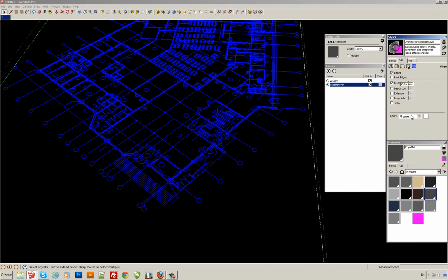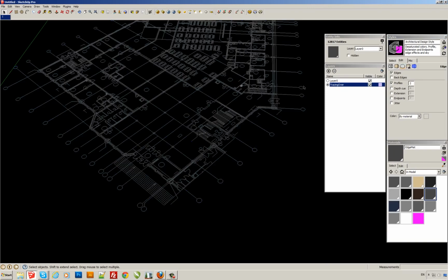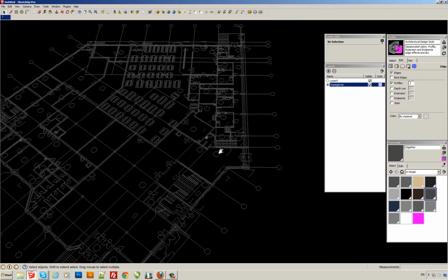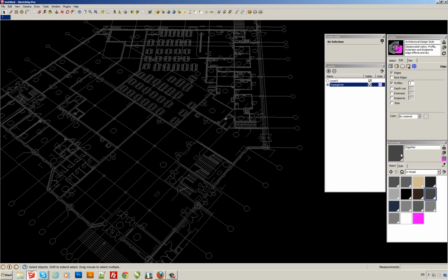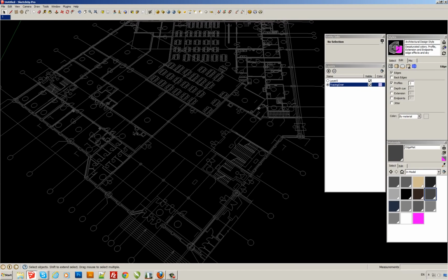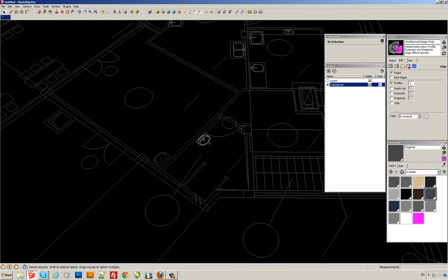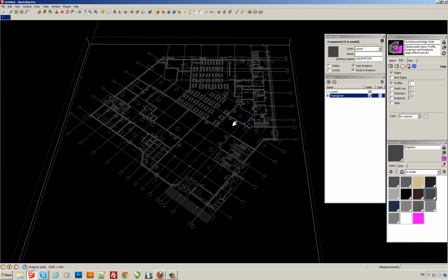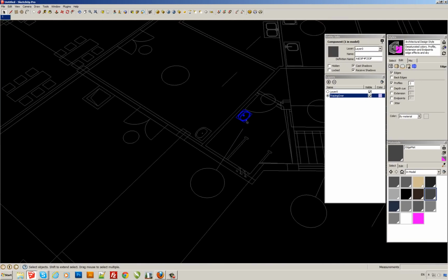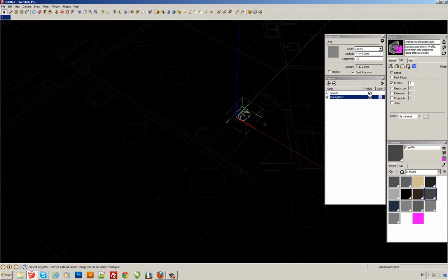The most important thing, we need to use the color by material, and this option will render our edges by the material which is applied to these edges. So now we are working on the edge color, edge matte, and some geometry. You can see which were blocks in the AutoCAD became the components in the SketchUp, and they are colored by different color inside the blocks.